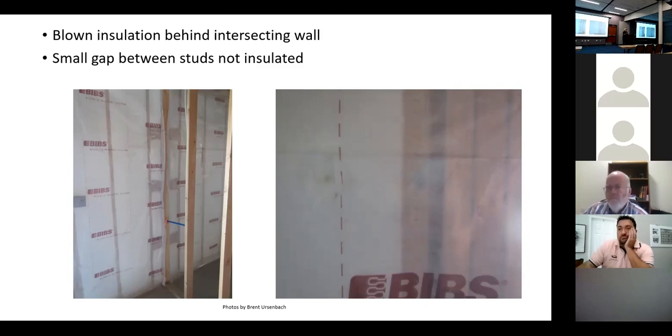Because it can't dry. Now, this wasn't a problem in the past because we didn't use OSB and the houses were really loose and they'd get wet and they'd just dry because of all the air movement through the house. I mean, the house I grew up in was diagonal 1x6, nailed on the outside. And it was the stuff they used for the forms when they poured the foundation. You guys have seen it.